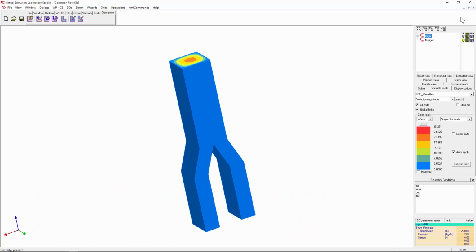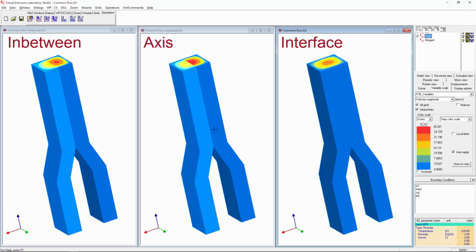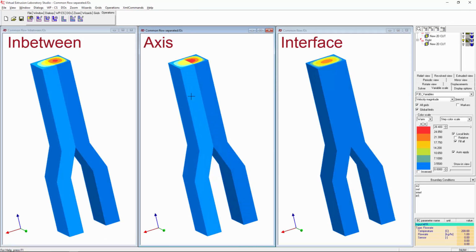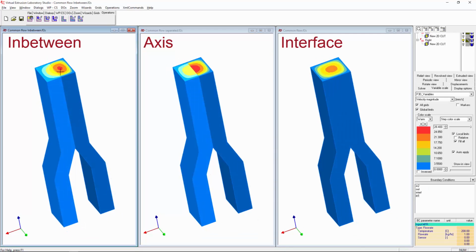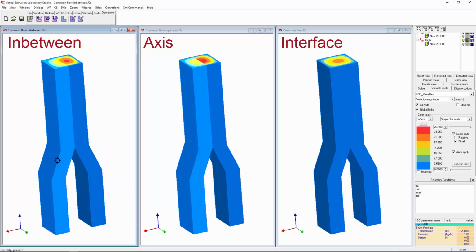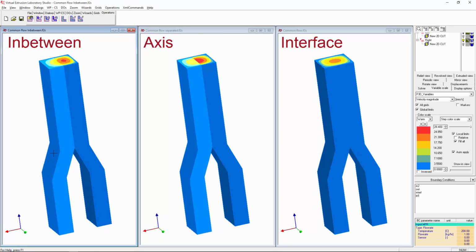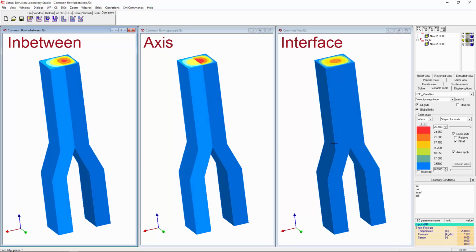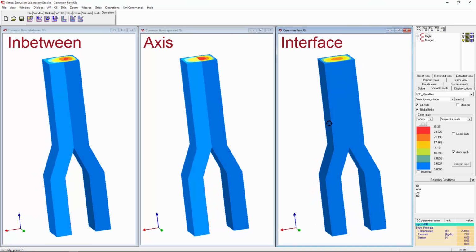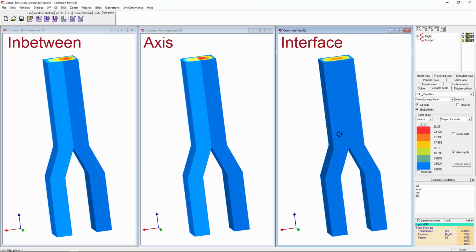Okay. We can have different methods for solving coextrusion. We can use a separated boundary with axis or a perfect slip wall. We can use an in-between boundary, which is very close to reality. And the advantage is that we can do these calculations very fast and also easily post-process. Well, the real case of coextrusion is, of course, this one.